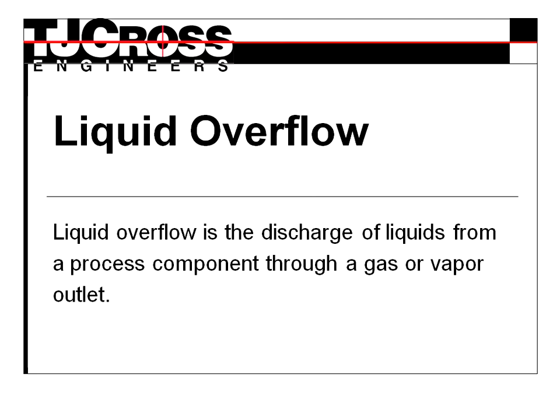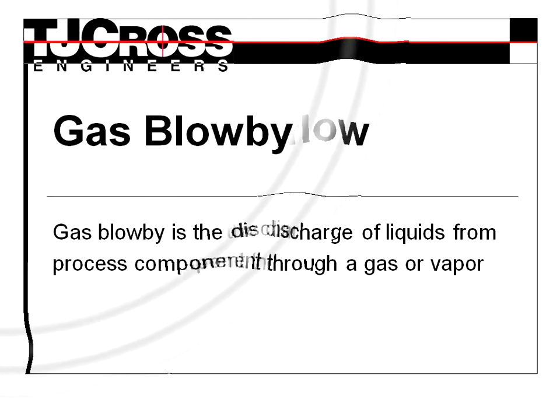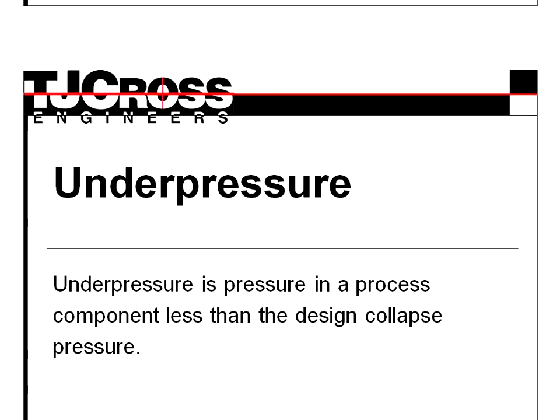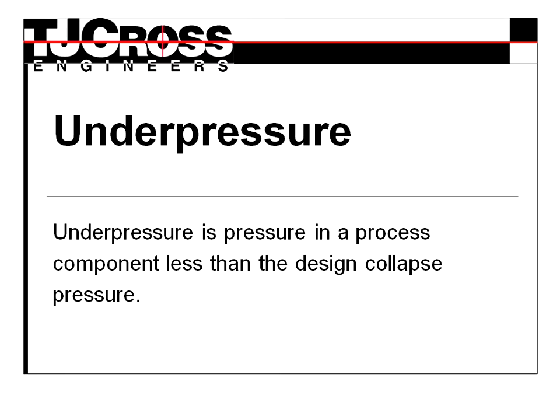Liquid overflow. Liquid overflow is the discharge of liquids from a process component through a gas or vapor outlet. Gas blowby. Gas blowby is the discharge of gas from a process component through a liquid outlet. Under pressure. Under pressure is pressure in a process component less than the design collapse pressure.